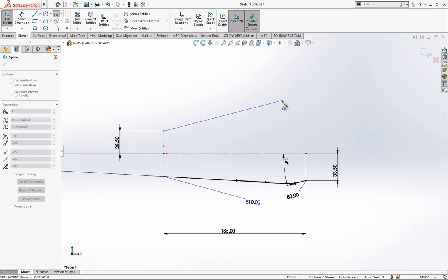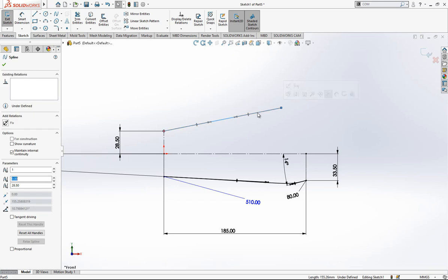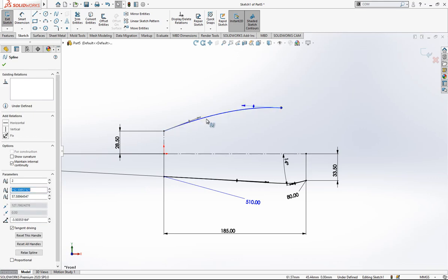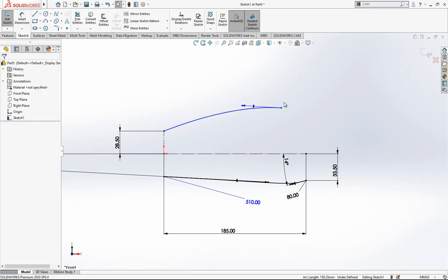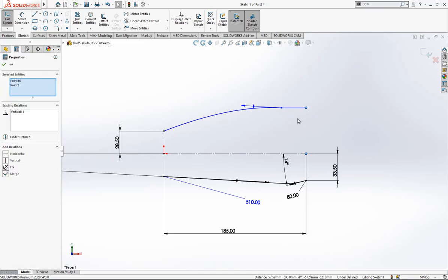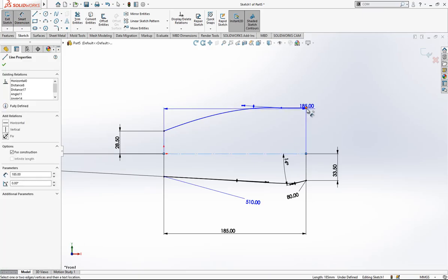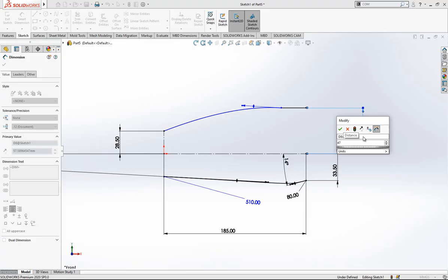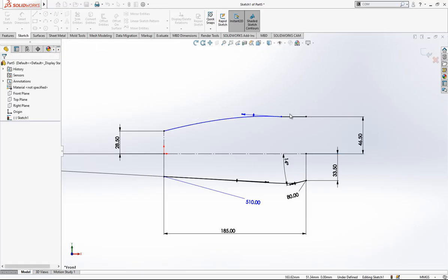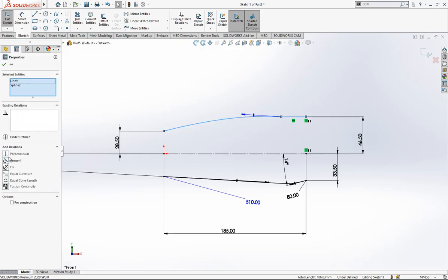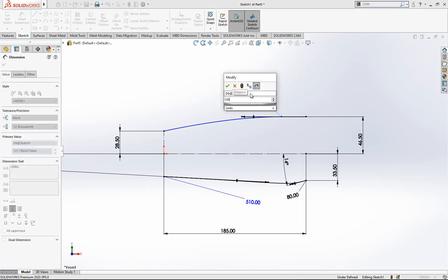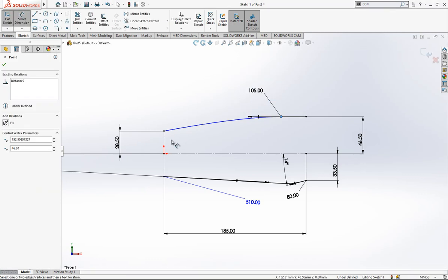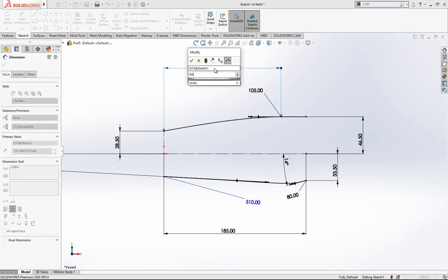Then the second we place here again a spline, a little bit play with that, and we can give some values before I'm going to add one line. These two points will be vertical. This point in 46.5 and having tangency with this, and tangency magnitude is 105, and this point at 165.